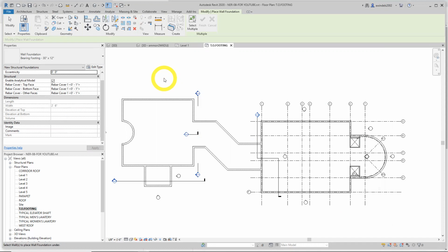And we're going to pick everything but the elevator shaft walls. So kind of similar to what we did already. Those are interior walls. So the 3D view will be huge again. We're just going to have to go slow. Tab here. This one's a little easier than the last one. You can see it populate because we changed our view range.